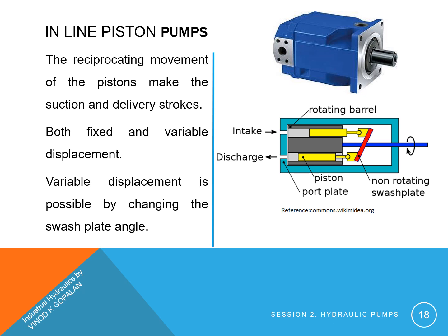In some designs, the swash plate angle cannot be adjusted, which makes them fixed displacement pumps. In some designs, this angle can be adjusted, which makes it a variable displacement pump.